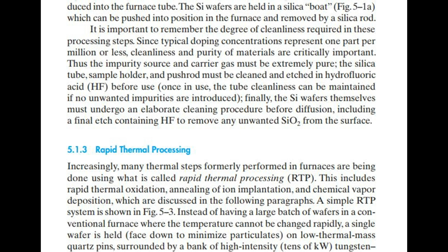Once in use, the tube cleanliness can be maintained if no unwanted impurities are introduced. Finally, the Si wafers themselves must undergo an elaborate cleaning procedure before diffusion, including a final etch containing hydrofluoric acid to remove any unwanted silicon dioxide from the surface.